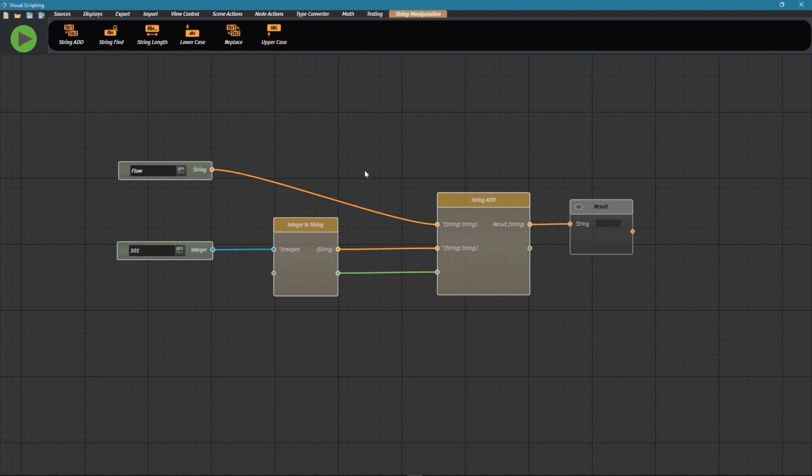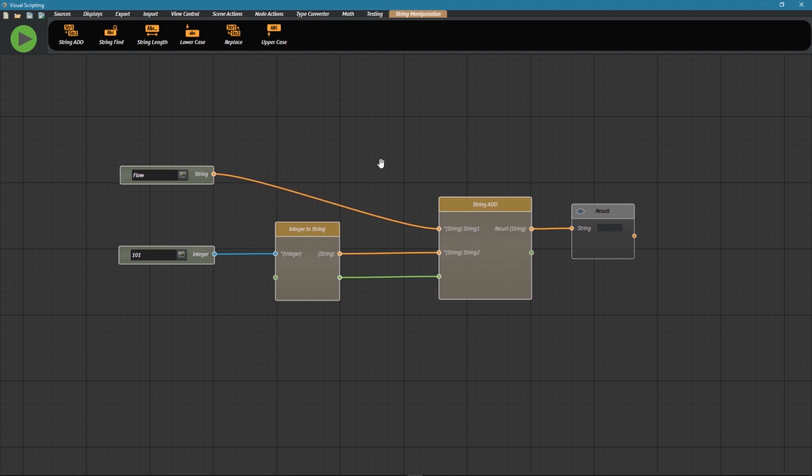Then the connections come around to make the whole flow meaningful by defining which source or block output connects to which block input, and also by arranging the order of the execution for these blocks. The green ports on the blocks are not essential, but they are very important to ensure the right execution order of the blocks, and to create dependencies between the blocks. The ports on the blocks are colored depending on the type of data that should be passed through each port. The connection between two ports represents the same color as well.